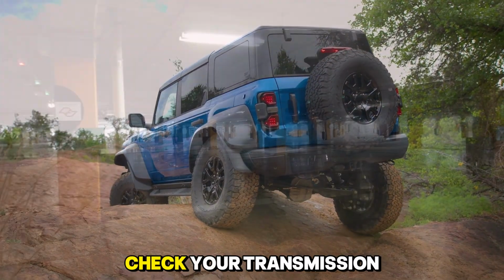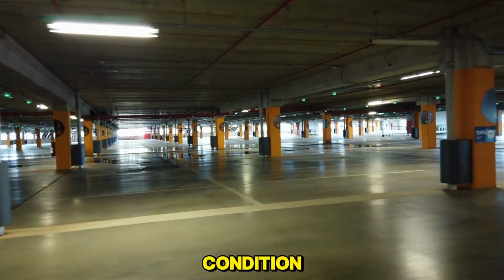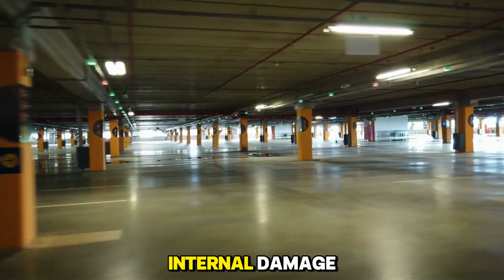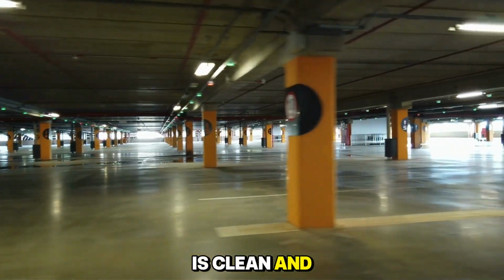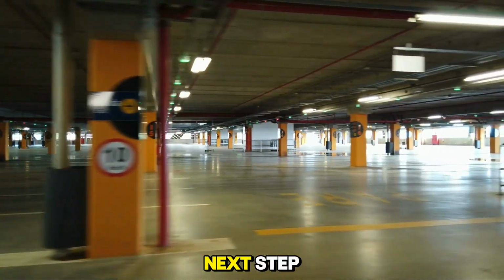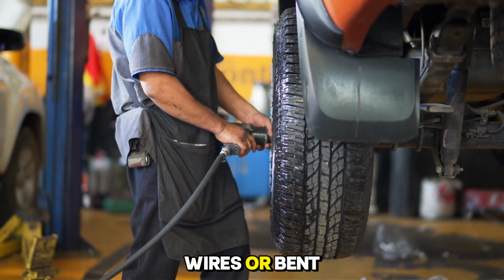Before you panic, check your transmission fluid level and condition. If the fluid smells burnt or looks black, you might have internal damage. If the fluid is clean and full, inspecting the wiring harness plugged into the transmission is the next step. Look for frayed wires or bent pins.